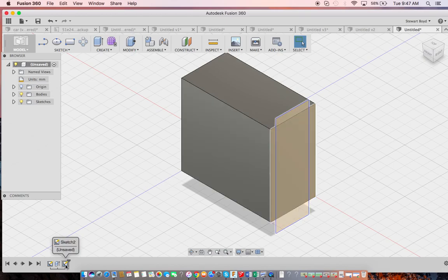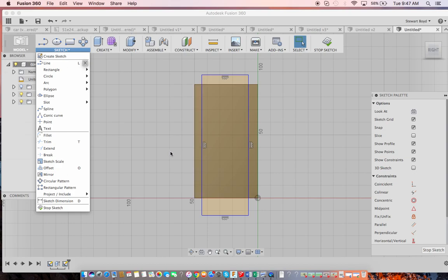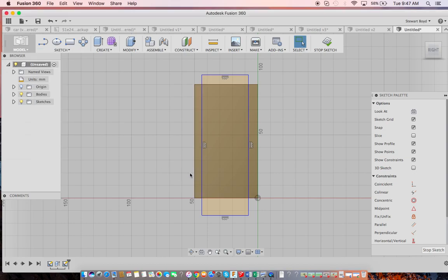So I'm going to pop back into that sketch, and I'm going to press D on my keyboard, and the D should, it's not doing it at the minute, sketch, escape, dimension, there you go, dimension from there to there, and it says at the moment 5. So I'm going to make that 7 and then press enter. The same from this side, click from this edge to that edge and make that also 7 and hit enter.